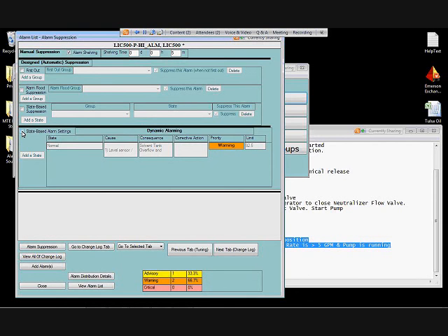Also, I know that this particular unit has problems with alarms when the equipment is out of service, when the solvent tank is out of service, and many of the other alarms in this unit are actually suppressed during that state. Now, this is a pretty critical alarm because it was identified in a HAZOP, so I don't feel that it can be suppressed when the equipment is offline like the other alarms. In fact, I think we should keep this alarm.